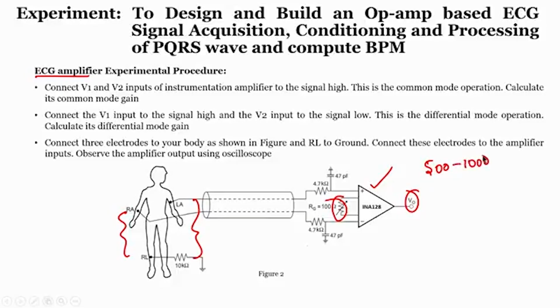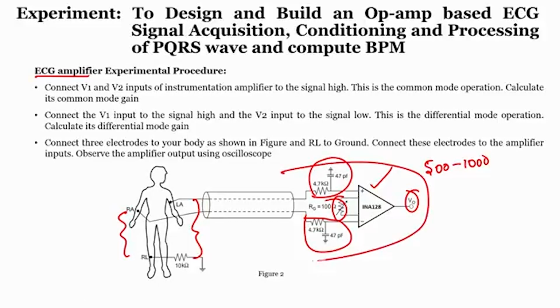Now, what is the use of this resistor and capacitor? This acts as a low pass filter. Any noise coming from the input signal will be removed. So, this circuit is completely the instrumentation or amplification stage of an AC signal.